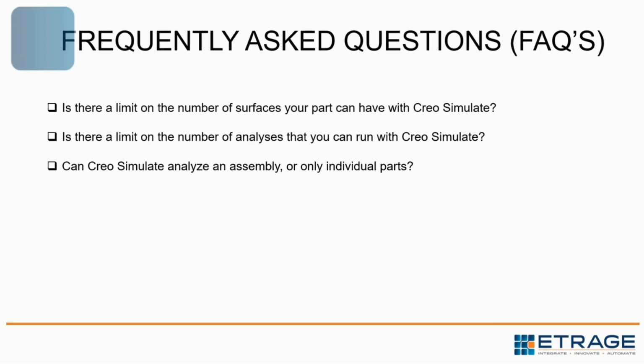But I believe recently, Creo Simulate is included with almost every base seat of PTC Creo nowadays, so you should be able to take advantage of just the regular Creo Simulate without the limit of the surfaces on any of your models. On those licensing specifics, I can speak to some of that. PTC removed that 200 surface limit for structural simulation, so all Creo seats now on subscription have that full structural simulation capability, but not the thermal and the modal.